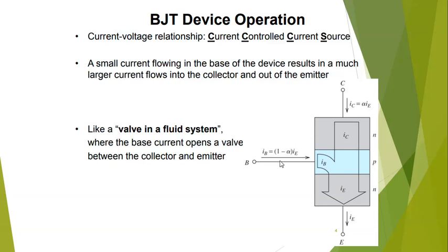All of this is happening using some currents. When it wants to tell the compressor to turn on, you can imagine it's sending some current to the base of a transistor, and that transistor lets the current pass through the compressor itself. In real life, that is not actually done using a transistor for air compressors. It's done using contactors or PLCs or things like that, some smart relays. But the basis of the operation is the same.